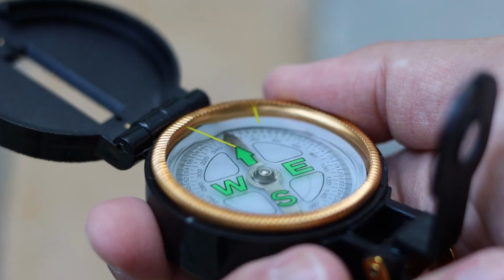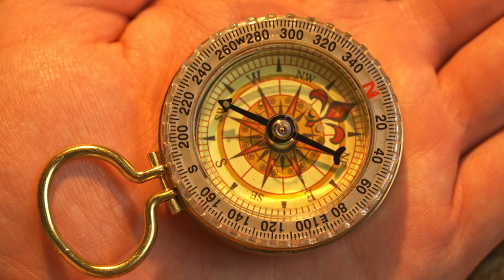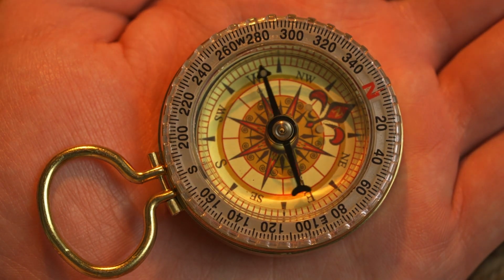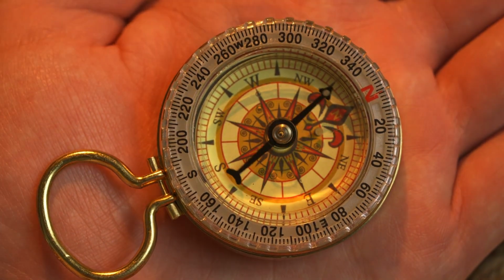Deviation west, compass best. Deviation east, compass least. Here are some examples to try. 1. Your true course is 114 degrees T. Variation is 4 degrees W. Deviation is 5 degrees E. What is your compass course?